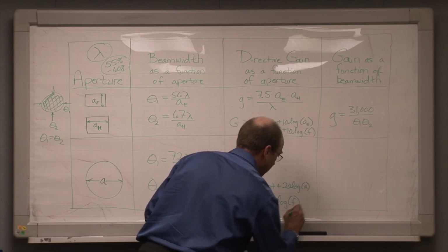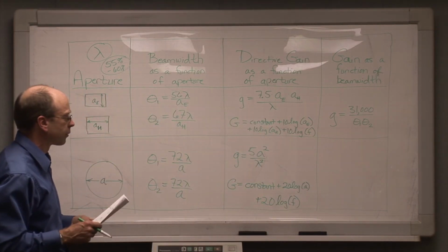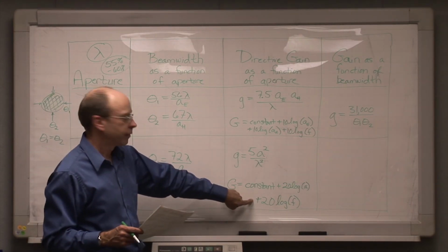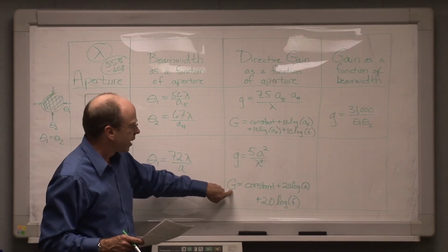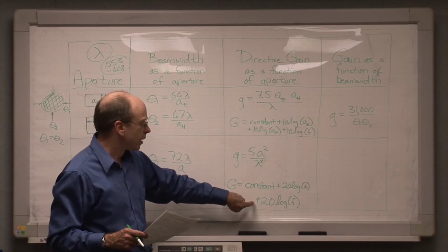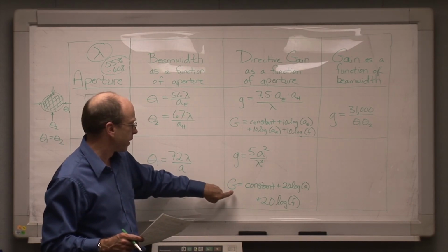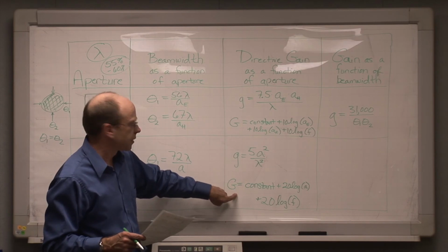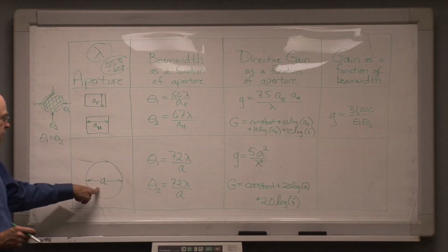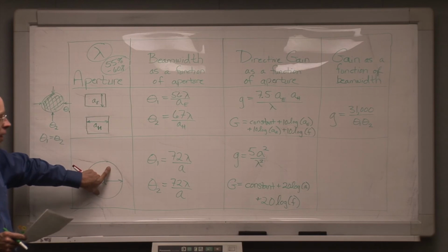And look at that. Remember that the effective aperture of the isotropic antenna dropped as minus 20 log F? Well, the gain of the dish relative to isotropic goes up as 20 log F. In other words, in terms of the aperture being presented, it's a constant aperture antenna. That's consistent with the fact that the aperture of this dish is constant.